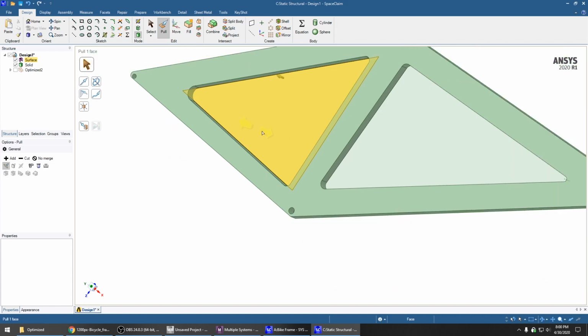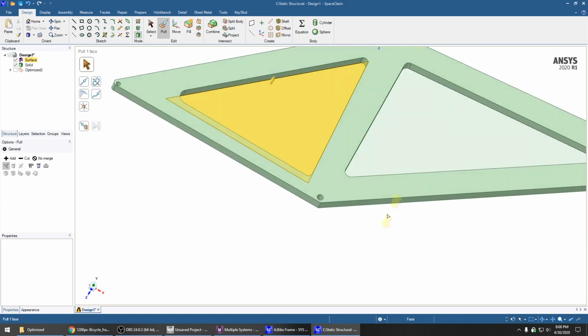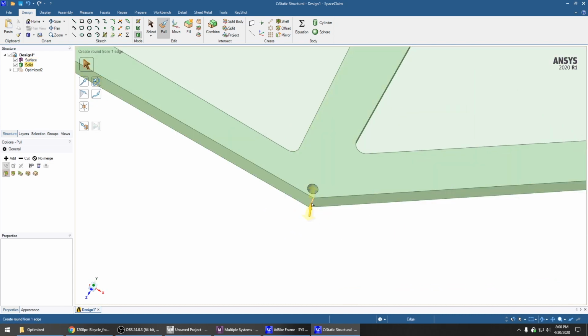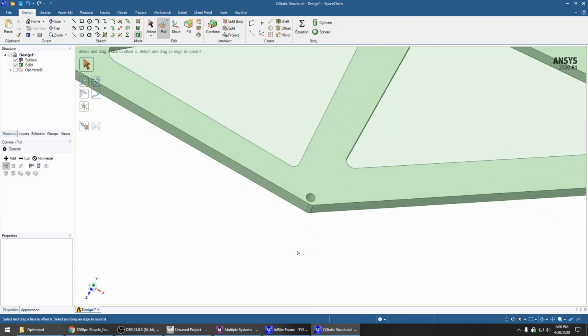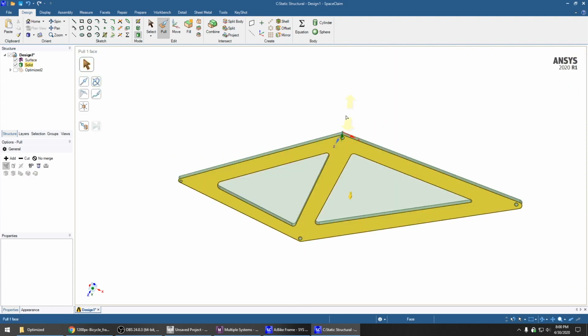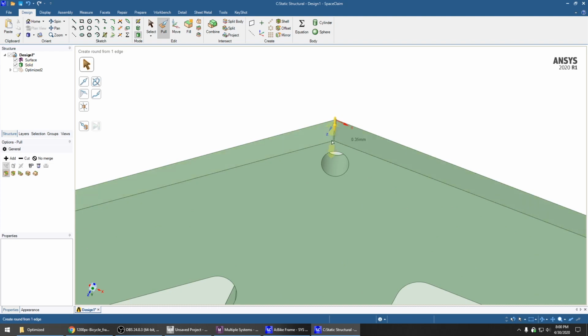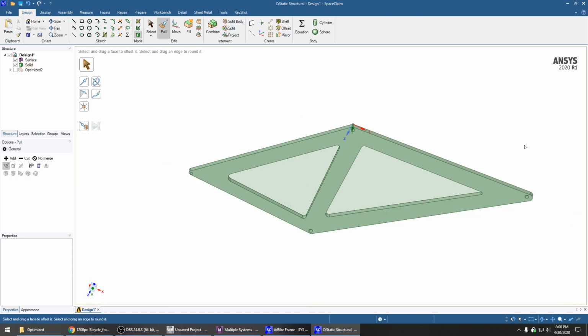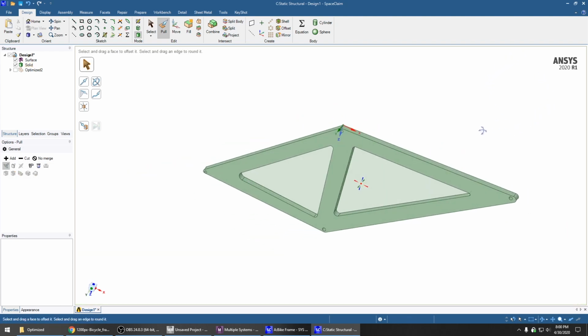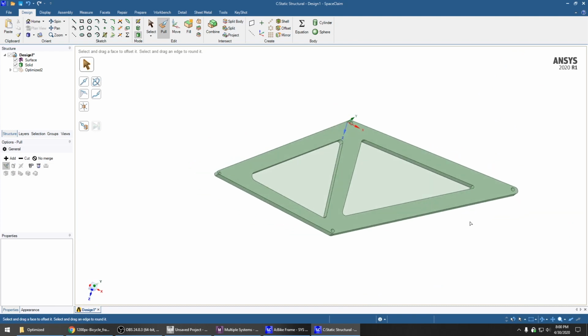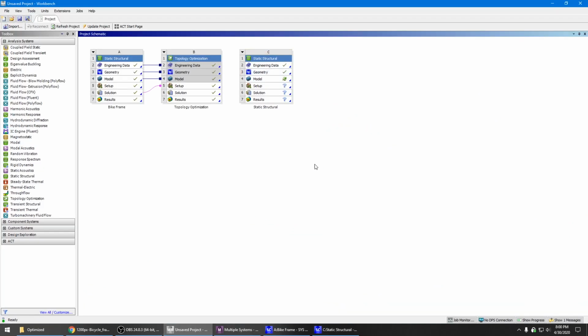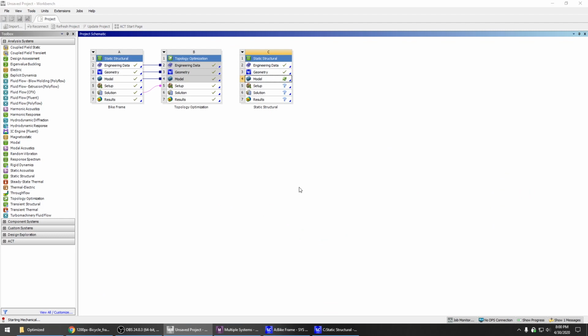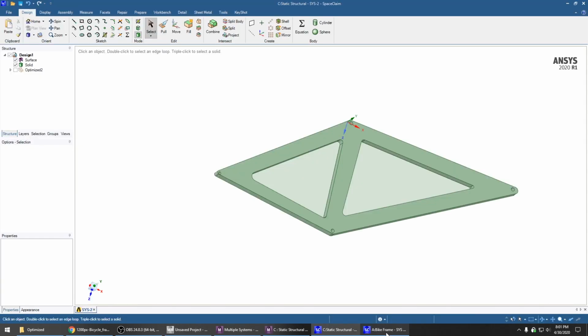Perfect. So if you can't radius the corners in the sketch mode, just go ahead and extrude it upwards like I did. Just use the pull tool, give it some thickness, and then you can still pull on the edge after the fact like I'm doing right now. And it should work. Okay, so we got nice radius corners everywhere, and I'm thinking this is gonna be a super strong frame. So let's take this guy and go back here, go and mesh it up and run the FEA again. So we're literally starting over with the new design and seeing if it actually passes stress or not.